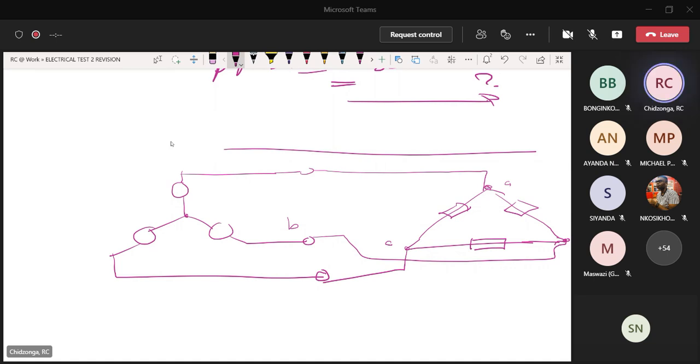So I told you that this side here, let's say there's 240 volts. For three phase, if I don't say anything, I just say 240, you must know that this voltage is a line-to-line. Three-phase system, we normally specify the voltage as a line-to-line. But if I say VAN equals 240, then I'm telling you this is phase voltage. So you can't just assume.